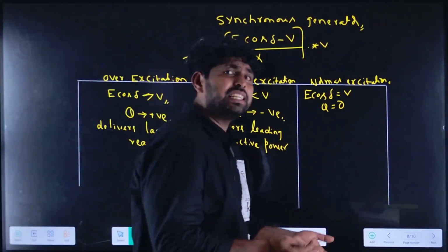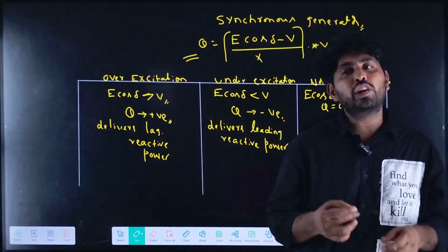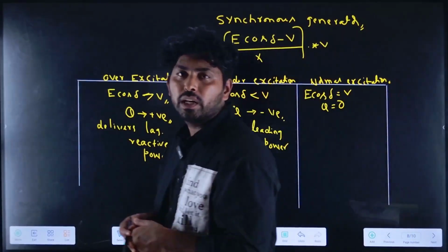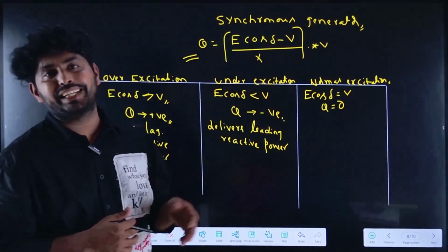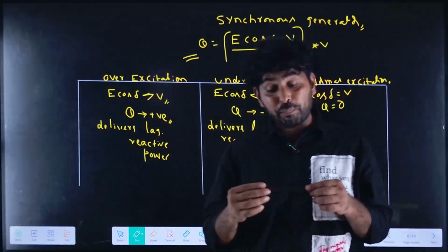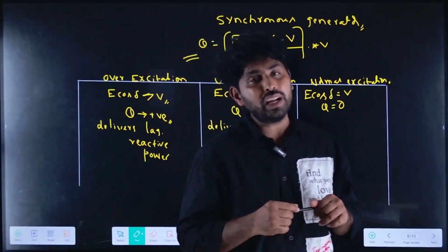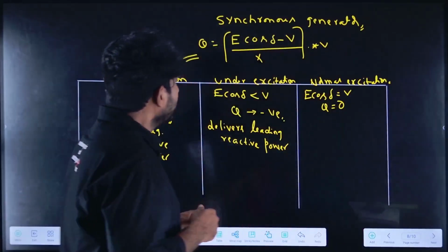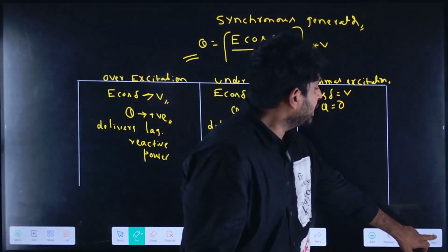And one more thing: in a synchronous generator, if you want to control the reactive power, we need to control the excitation. If you want to control the active power, we need to control the prime mover input. Now, the next one.